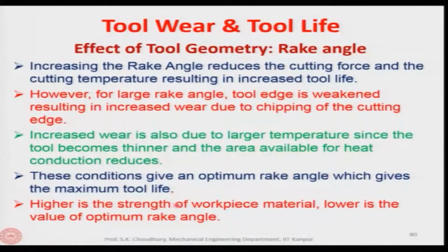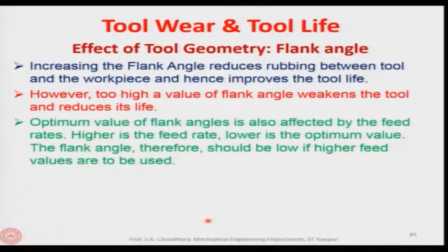Higher is the strength of the workpiece material, lower is the value of the optimum rake angle. It is obvious. If the strength of the workpiece material is higher, the force required will be more, and then it will reduce the tool life.